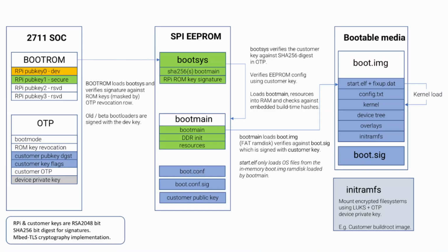The next step is to figure out how to change this value. As I mentioned before, the boot main is signed, so we can't just change this value in the boot main, put together a new firmware file and flash that on our Raspberry Pi 5. That's just not going to work. However, we can try changing it at runtime. And for this purpose, we memory map the system memory of the VideoCore on our device. We find the function that governs the upper voltage limit, and then we change that value at runtime. And then we hope our Raspberry Pi 5 doesn't go up in flames.